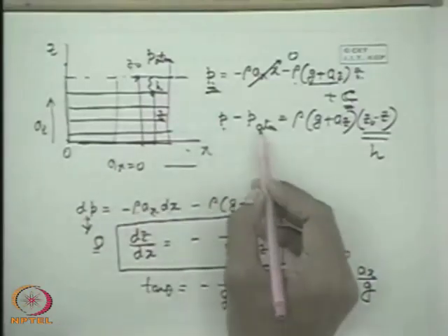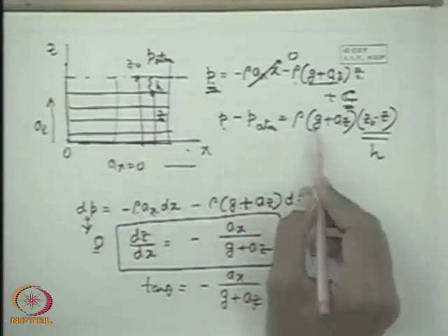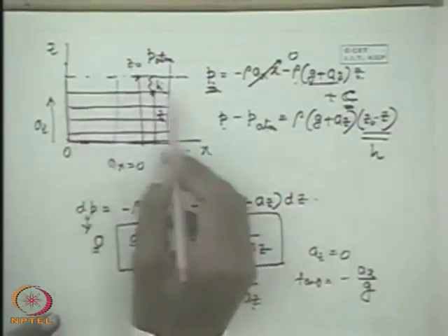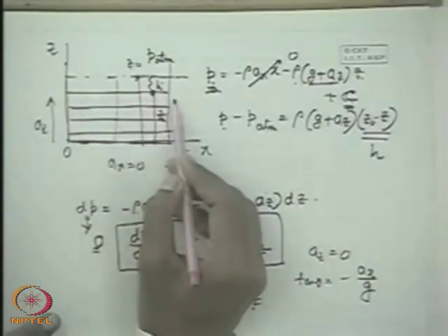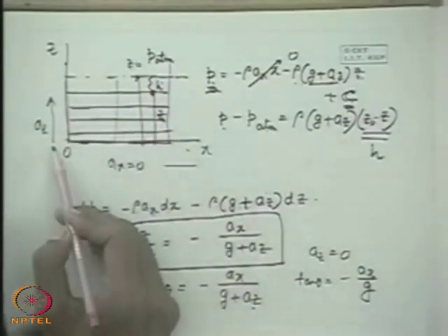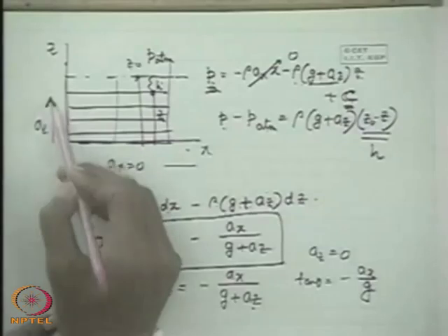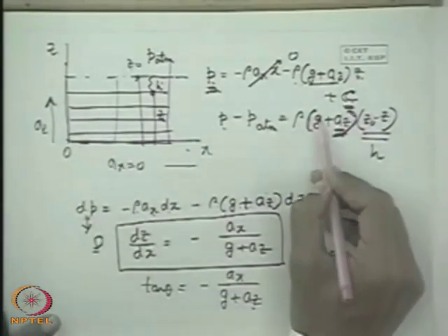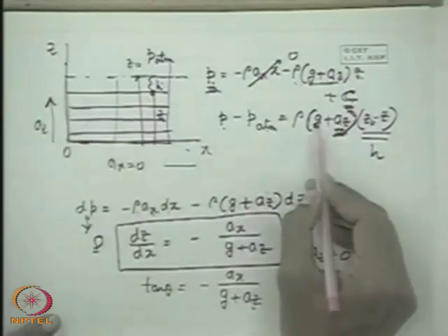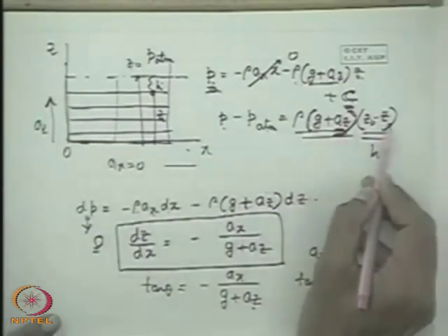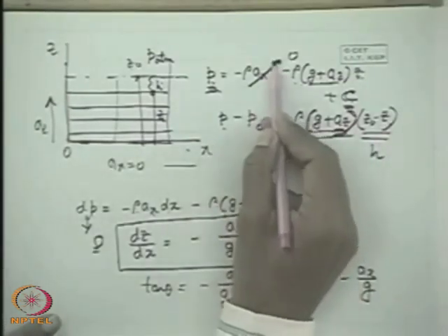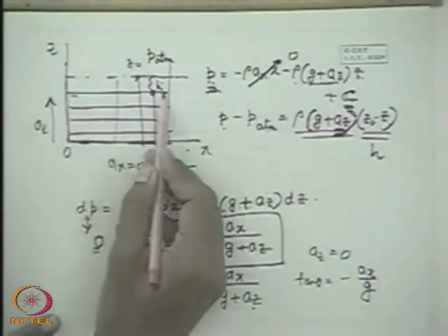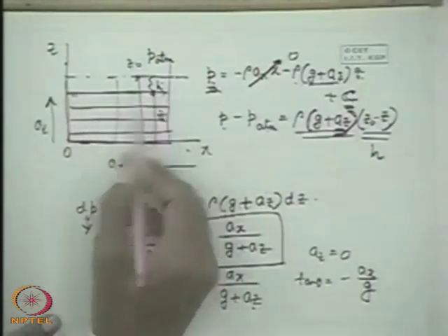we know the pressure is more than the atmospheric pressure by rho g H in case of a static fluid or fluid moving with uniform velocity. But in case of a fluid moving with uniform acceleration in z direction, the contribution of z direction acceleration is to change the g. That means it is increasing g by g plus az, so take care of that. Alright. If there is no acceleration in x direction, there is no variation of pressure in the x direction. So lines will be horizontal.